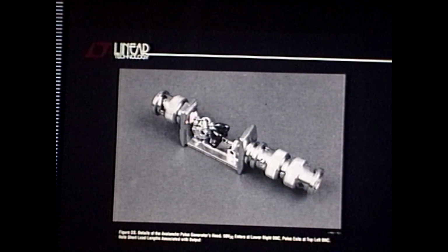So you can see, within the limits of discrete technology, I've mashed this up as close as I can. Practically speaking, BNC connectors really start running out of gas at these frequencies. The real way to do this is a type N connector, or the beautiful old General Radio hermaphroditic things, which are probably the best connectors ever built at frequency. It's just GR and Tek were the only guys who ever used them, and Tek gave up on them because everybody wanted to go BNC. But in fact, I think the avalanche circuit may be running faster. You've just got too much parasitic here.